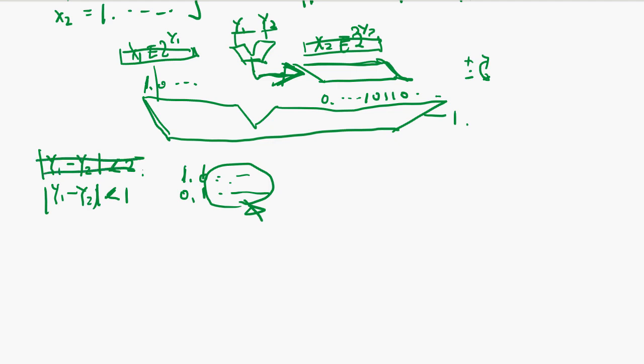We have to consider this case, right? The difference is only 1, and if it's 1, the case is like this. So after subtract or add, it may shift right or left by 1 in order to bring the format back to leading 1, so and so, right?